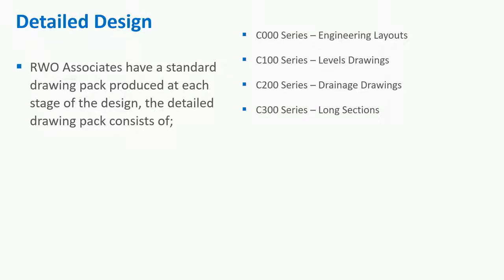You've got your long sections, which is your road alignments, which could have your projected drainage on them, but if your drainage is off-site, it will just be typically your drainage alignments projected on. We've got our road setting out. This is just produced with another label set with a click of a button. Within the alignments, profiles, and corridors M3 file, we can quickly change everything, and there's a full pack of setting out there ready for the developer, saving them some time.